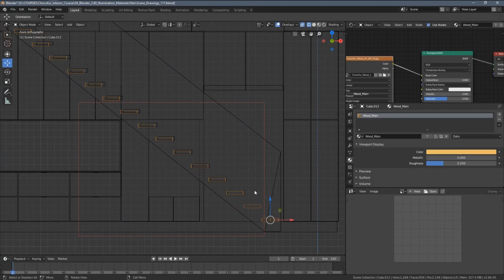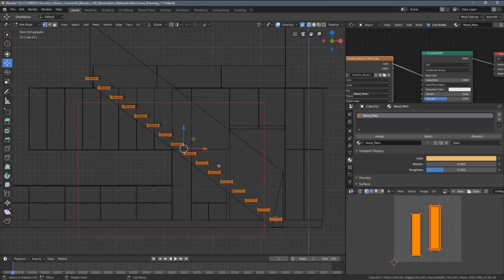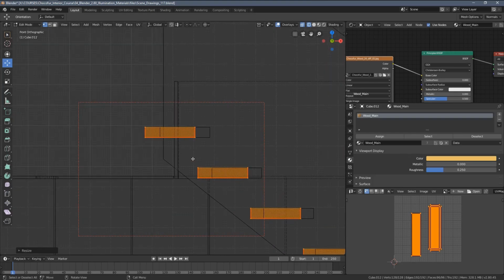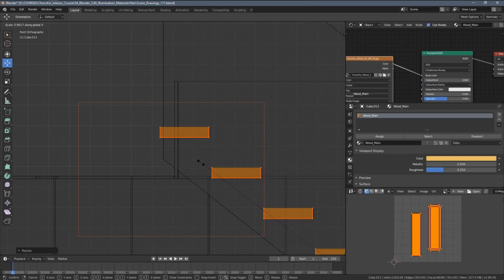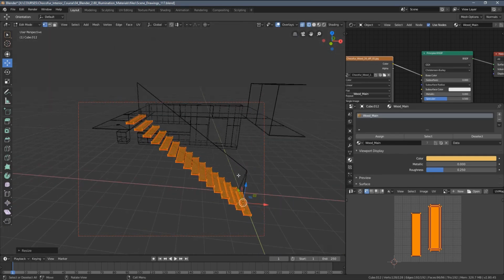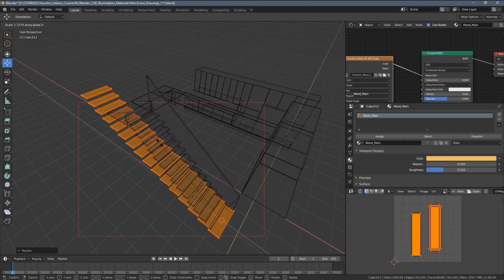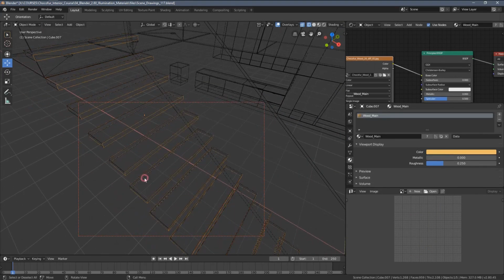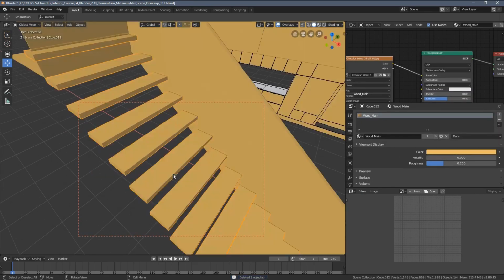Let's now focus the 3D cursor around our first step, cursor to selected, select everything, change the pivot point to 3D cursor, scale Z to align those elements on this axis, and now X, S, X to move them around in this axis like that. So you can see we have this UV mapped element recreated.